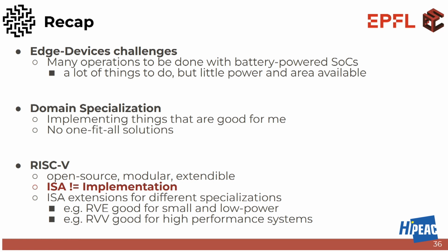We made some examples. Some of you suggested let's use clock gating, power gating to reduce the power. That is a generic optimization that is always good to have, and it's usually domain independent. Then there are other optimizations that are domain dependent. So for example, adding extensions, customization, accelerators for those functionalities that you want to be good at. For example, FFT, security, and whatever else.